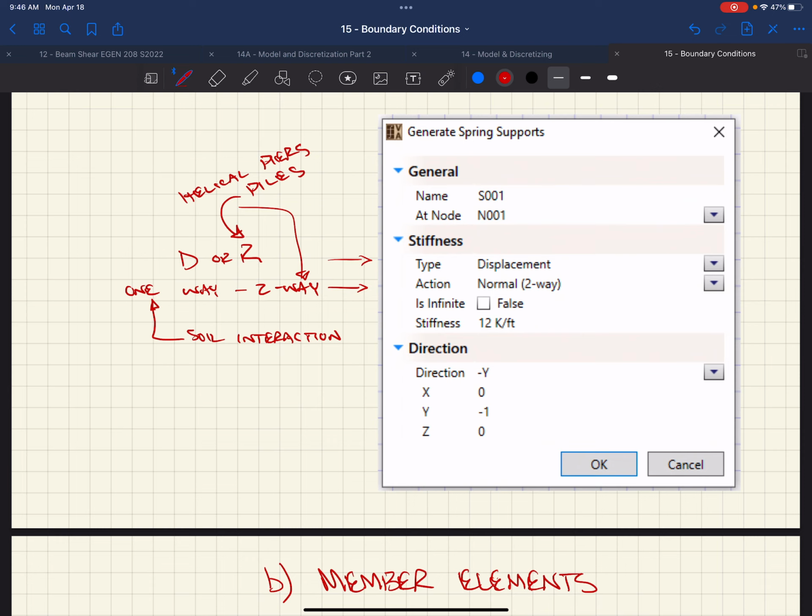But if you got a house sitting on helical piers, how do you cast in, I guess you could with tiebacks. If you've got a not heavily loaded house with 200 helical piers over a 5,000 square foot house, yeah? I mean, that little bit of lateral cantilever resistance adds up. Oh, for sure, and if you felt comfortable with doing it, the thing is, when you look at that helical pier sitting in the top of the soil, right? The top foot of soil really isn't going to, it's like you take a fence post and you push on it, right? And that fence post in the ground, the top like 6 inches of the dirt really easily starts pushing away, right? Yeah. And your real lateral resistance is down deeper in the soil.